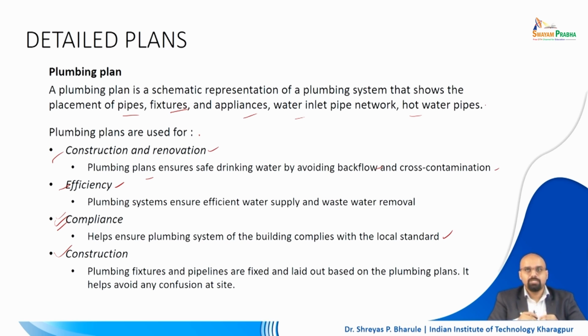So in that case, you need to identify the location of this cistern, place that cistern in a certain way, and draw the location of this, and all of this needs to be completed before you reach the stage where your brickwork is complete and you are about to plaster it, because that is the point you can put in the cistern. It is extremely difficult and expensive to deconstruct a constructed building after it is plastered and then go for concealed plumbing, because that will cost you a lot. So in that case, a complete plumbing layout helps a lot, right.